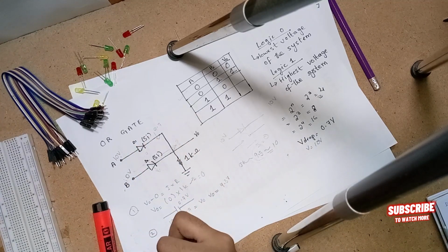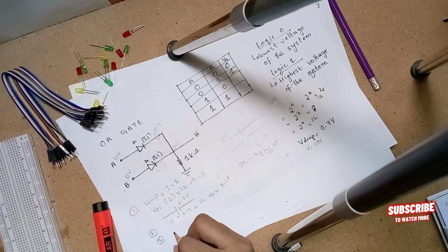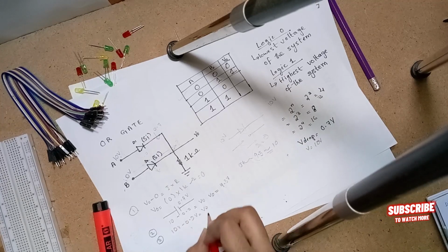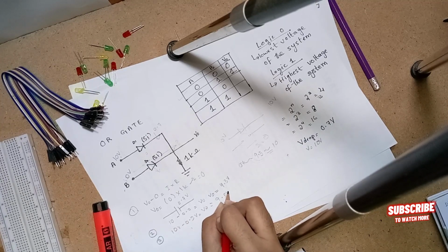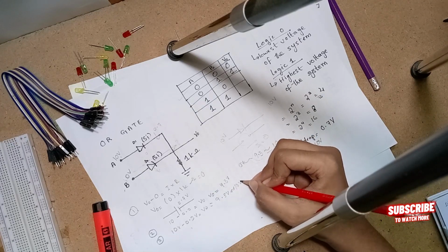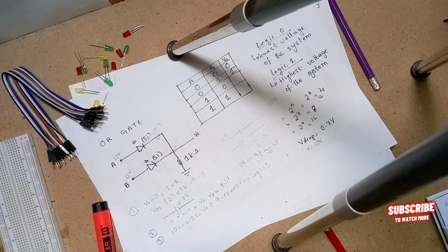So even in the third case, when we apply KVL at this node, we are again going to get 10 volts minus 0.7, which is the drop, equals V naught, which is again equal to 9.3 volts. And this 9.3 volts would be rounded off to 10 volts, which refers to logic 1, right? So in this case, we are again going to get a logic 1.